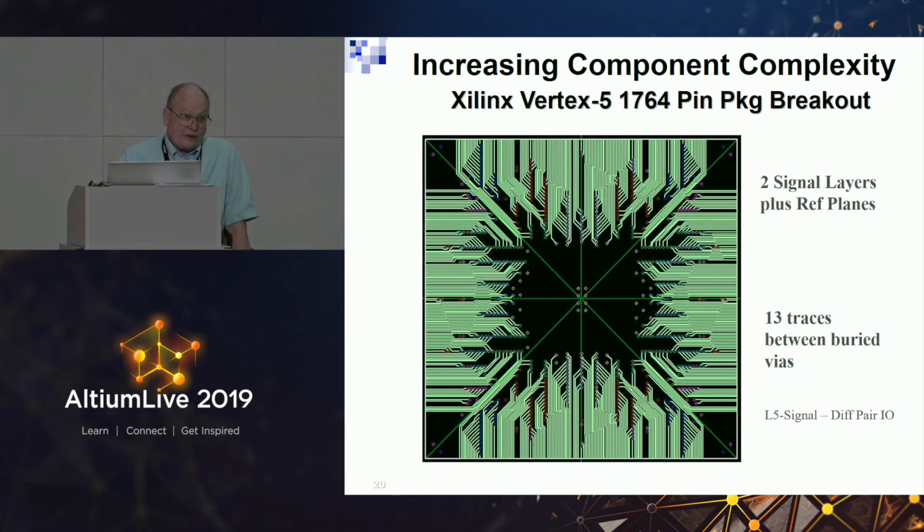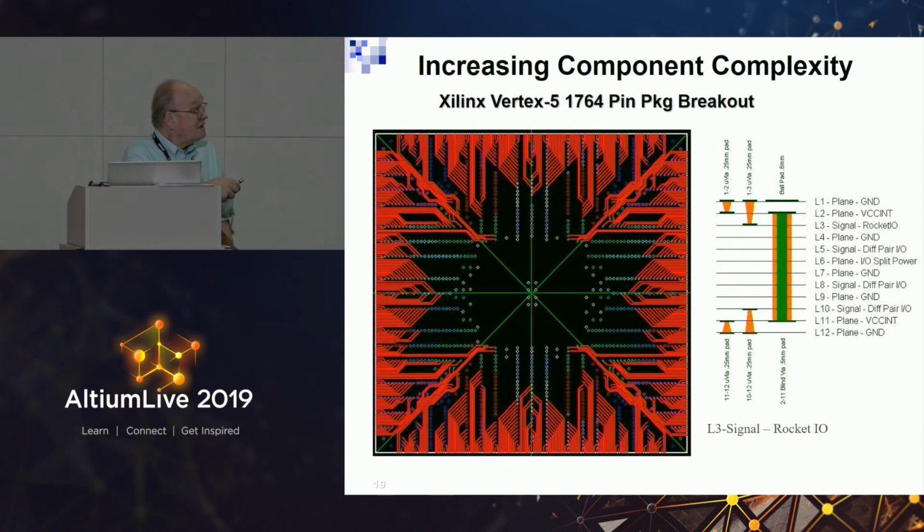I typically end up doing it on 2 layers, saving the money and everything with it. Because the problem with 6 layers is we now have crosstalk, a lot more crosstalk issues than doing it this way. You notice between layer 3 and layer 5, in this area right here, we've thrown in ground planes to isolate the micro vias from the through holes. That's because the through holes transmit noise. So for the most sensitive nets, we try to keep them as far away from any through hole as possible, because we pick up noise through the through holes.